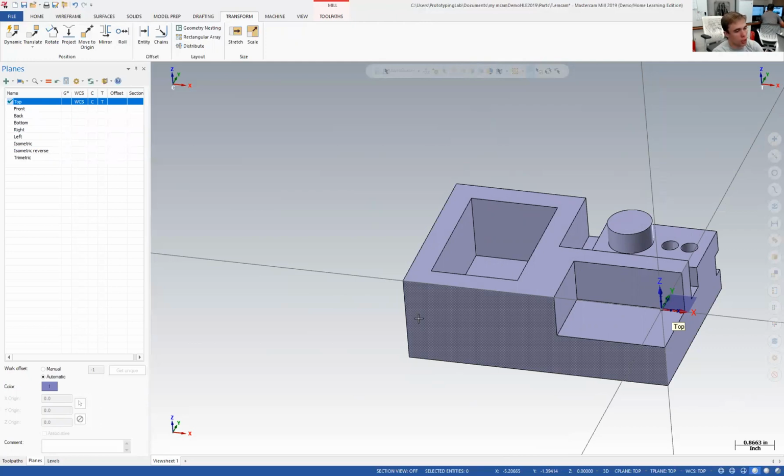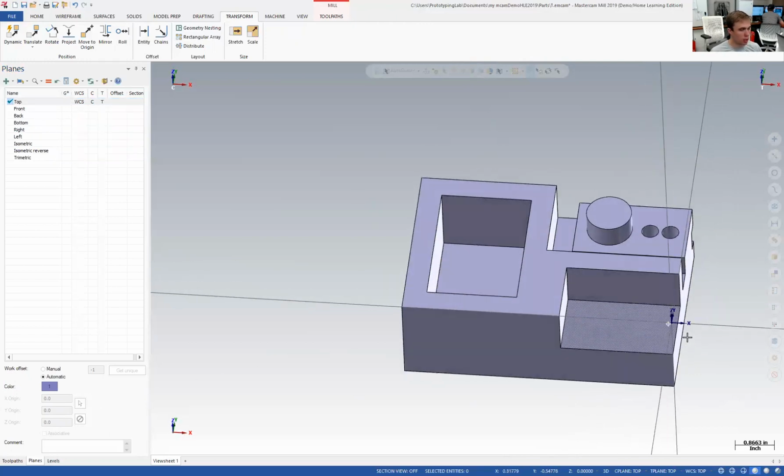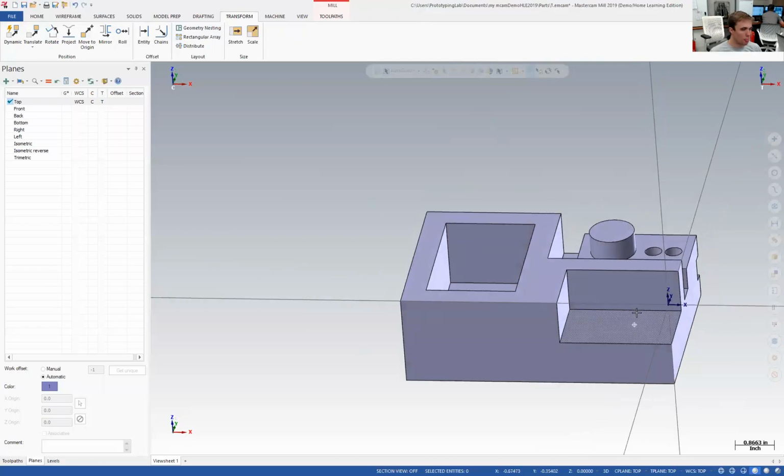For our Haas machines, if you open the door, you're standing in front of the machine, you open the door and look into the machine, you are looking along the positive y-axis. And running in front of you, off to the right, is positive x. And then positive z is obviously up.